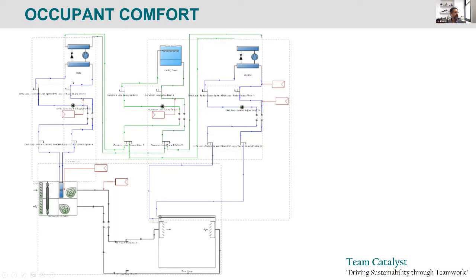Now, both of these are water-cooled chillers, so they are being cooled, in this case, by a single cooling tower. The condenser side of this chiller is connected here, and this chiller also, condenser side, is connected over there, okay? And there's controllers everywhere for each of these loops, and setting them up to be consistent is half the battle when you try and do a system like that.